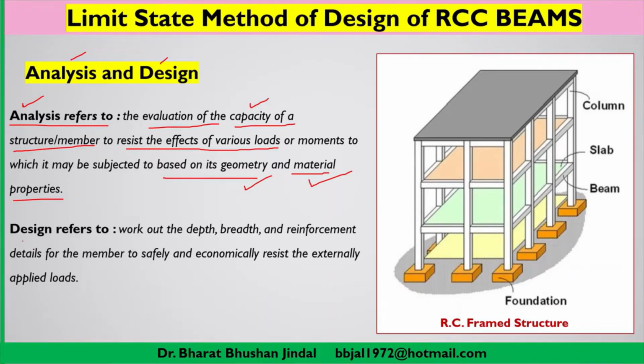Now let us briefly discuss the meaning of design, so that we should never get confused about the meaning of design. Design means working out the depth, breadth, etc. That means working out the dimensions of the cross section of the member, and the reinforcement details which we are going to use in case of an RCC structure, for the member to safely and economically resist the externally applied load.